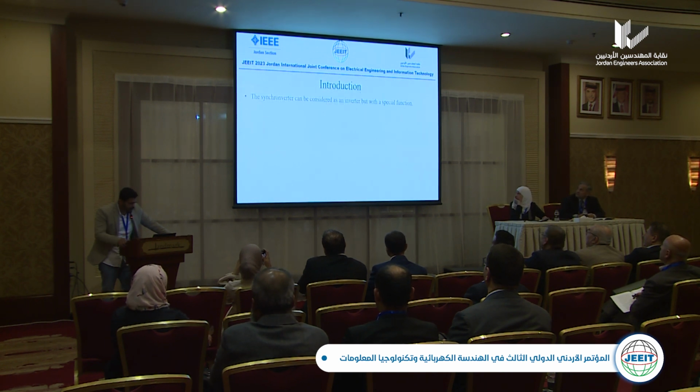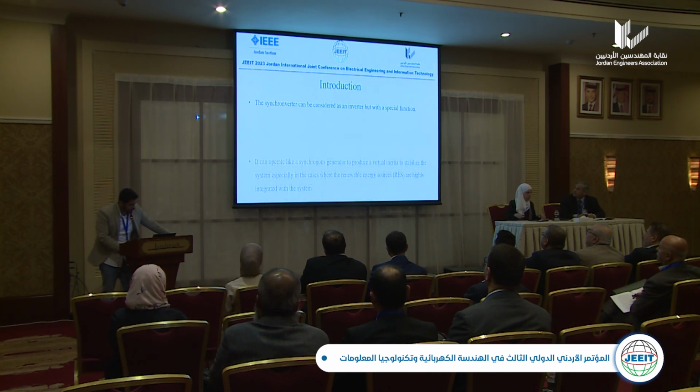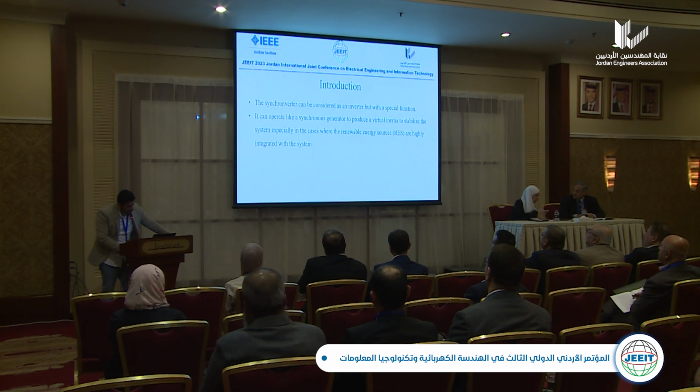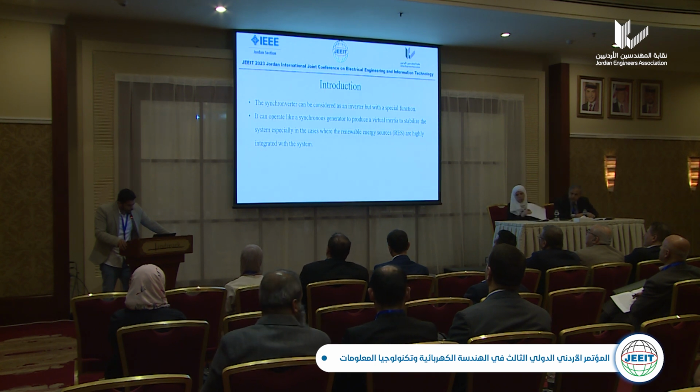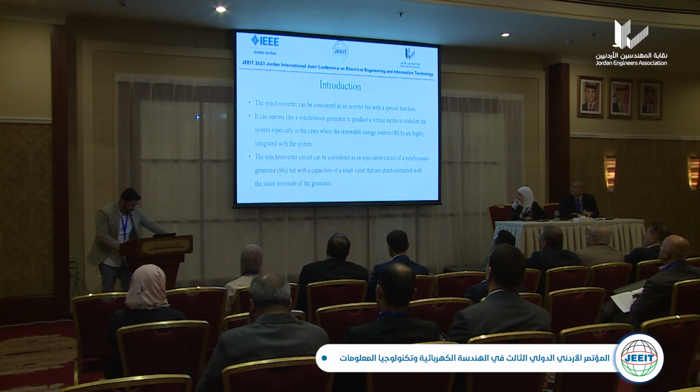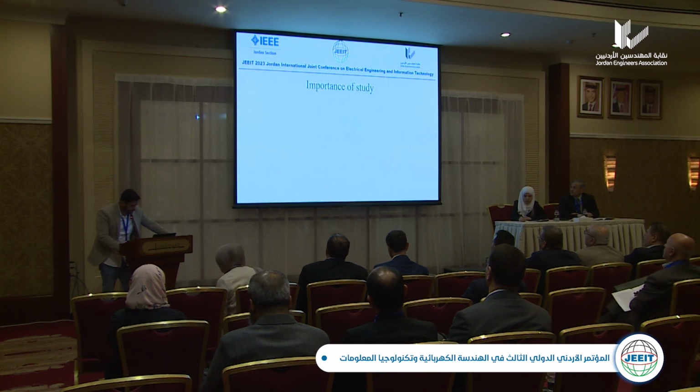The synchronverter can be considered as an inverter, but with a special function. It can operate like a synchronous generator to produce a virtual inertia to stabilize the system, especially in cases where renewable energy sources are highly integrated with the system. The synchronverter circuit can be considered as an equivalent circuit of a synchronous generator, but with capacitors of small value that are shunt connected with the stator terminals of the generator.